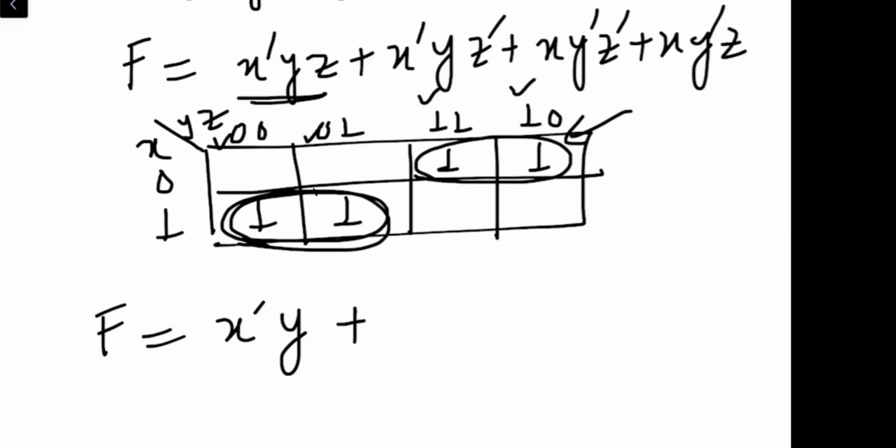So in the 2 adjacent boxes, y complement is not changing, and in the horizontal direction we have x. So this means we can make a group x, y complement. Are you with me? Yes, sir. Right? So we can make groups like this, and if you see, with this we are able to